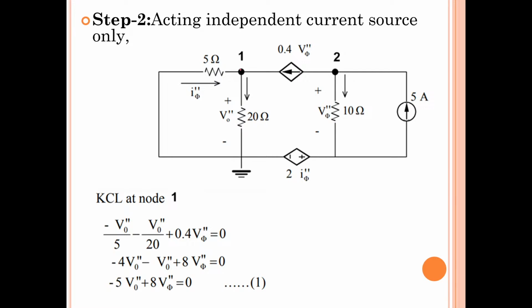So now see here, already a current source is there. Dependent current source. Its direction is towards the node. Other currents you can assume either all entering the node or all leaving the node. Here I have assumed a source current, of course the dependent source current's direction is already mentioned, we can't change the direction. So I have kept it as it is, and in this 20 ohms I have assumed current is leaving the node, and in 5 ohms I have assumed current is entering the node.